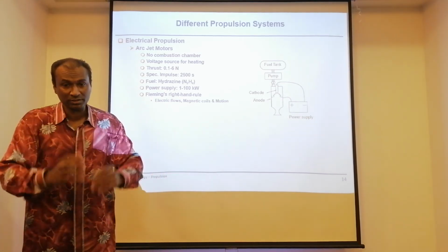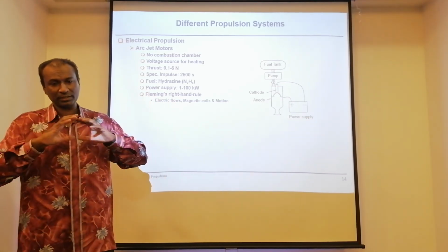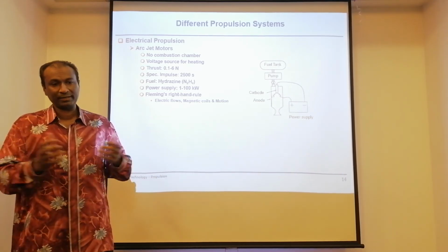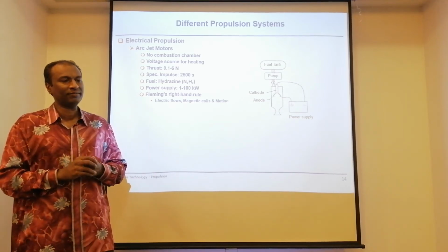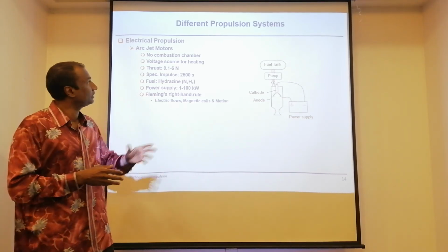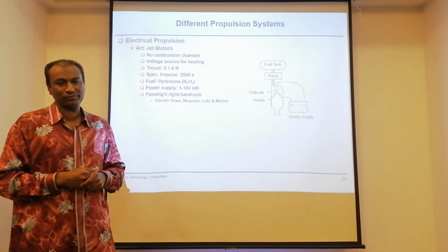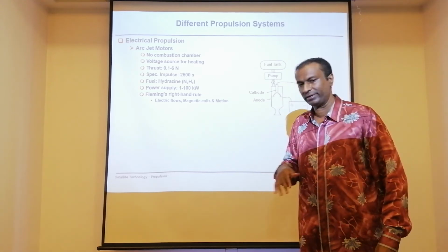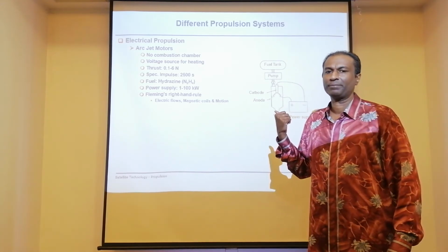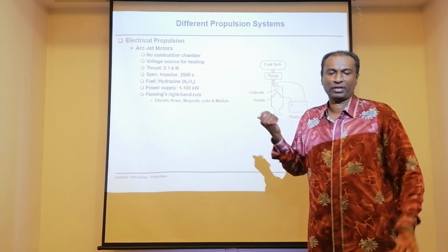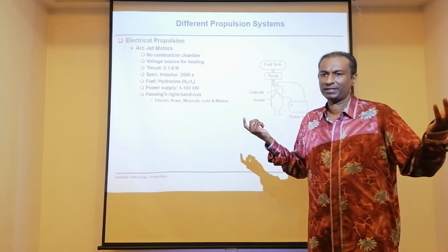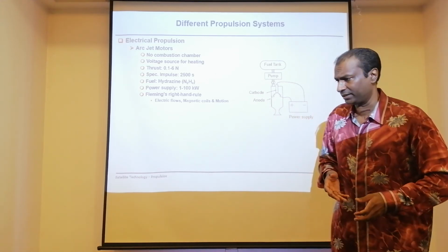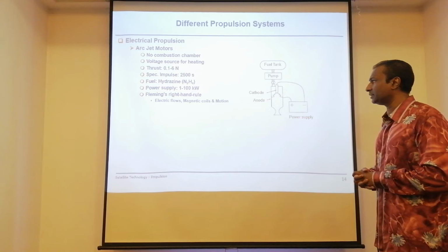So in Earth-bound missions, like Earth observation, small satellites, Flying Laptop, CubeSat, etc., you wouldn't find electrical propulsion or even arc jet motors as an option. If you want to fly an Earth-oriented mission, you may want to look at the bipropellant options that we have. You can typically use hydrazine, monomethyl hydrazine (MMH), and an oxidizer, N2O4, which is nitrogen tetroxide.